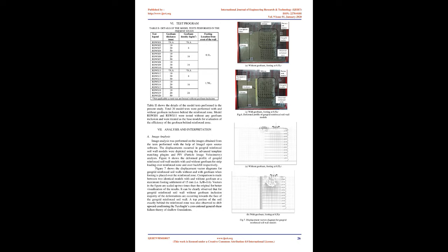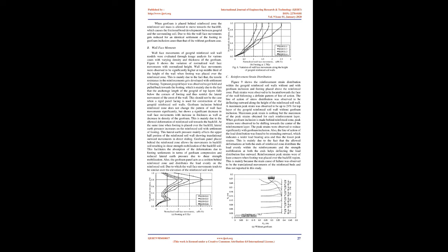Angle of internal friction at 85% relative density, 38. Geogrid. Ultimate tensile load, TULT, kN/m, 3.8. Ultimate tensile strain, percent, 24. Geofoam. Geofoam type: expanded polystyrene. Geofoam legend: F1, F2, F3. Density, kg/m3: 8, 16, 24. Compressive resistance at 2% strain, kPa: 17, 42, 74. Compressive elastic modulus, kN/m2: 850, 2100, 3700.